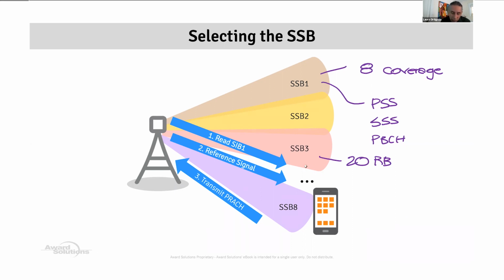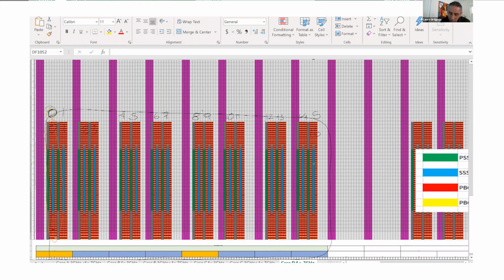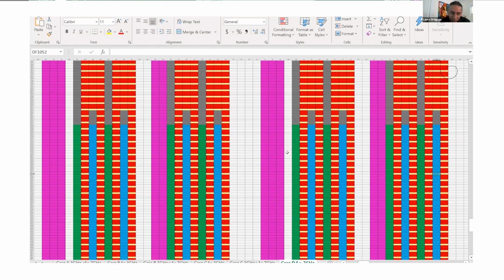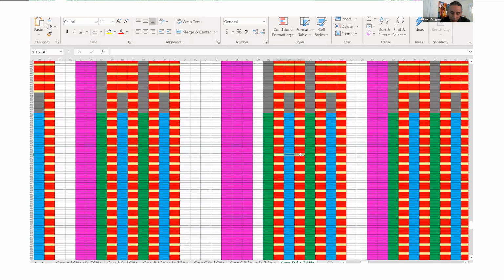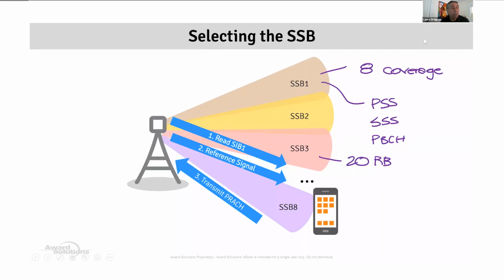Via the RACH. Cool. So in the uplink, I have to do RACH. I already know in which coverage beam I am. Remember, coverage beams only transmit control information. In this case, the UE already knows the PCI by the primary and the secondary synchronization signal, and it also knows the master information block. Now the UE needs to perform RACH. How does it do it, Lauro?